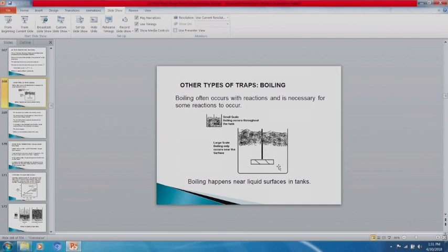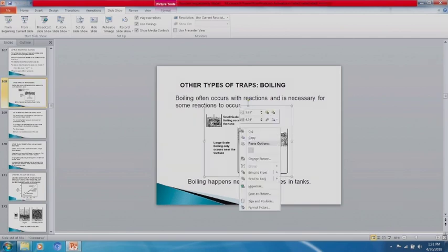There's a much higher pressure down here. As a result, boiling is a surface phenomena, correct? And it was required for the production to have boiling to occur. As a result, a substantial drop in production here due to the fact that only 1/3 of the reactor was being utilized. The scale-up should not have been geometrically similar, but instead, let's go into this again.